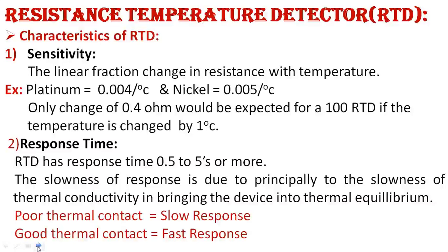The second one is the response time. An RTD has a response time of 0.5 to 5 seconds or more, the slowness being due principally to the slowness of thermal conductivity in bringing the device into thermal equilibrium. With poor thermal contact, the response is slow. With good thermal contact, the RTD gives a fast response time.